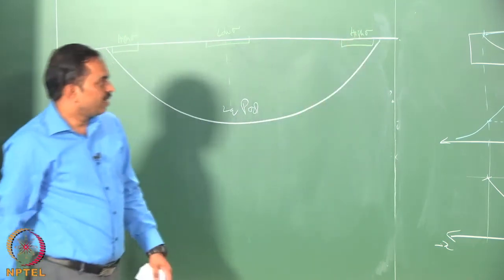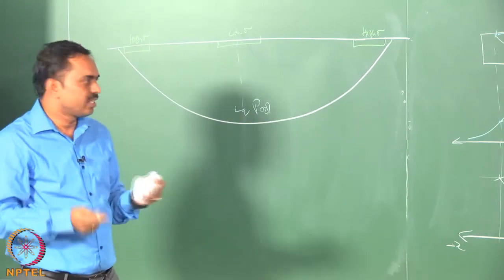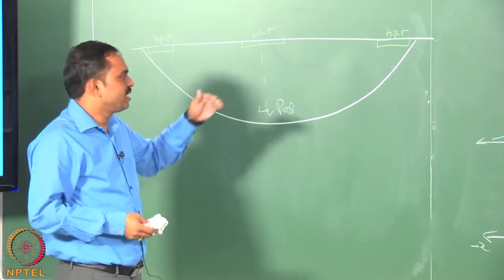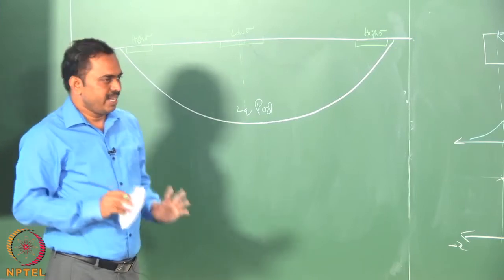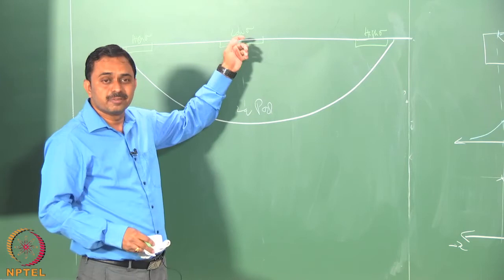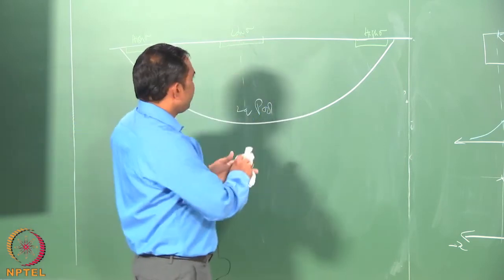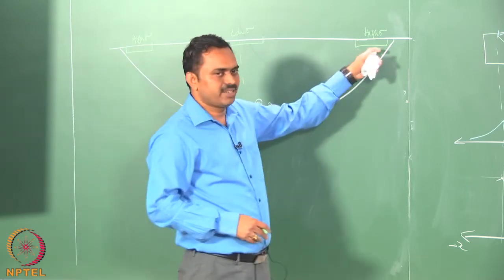And the reason why the liquid in the melt pool is going to convect because of surface tension gradients is essentially to minimize the surface energy contribution from the whole surface, and the way it can minimize is by having more area with low surface tension, or smaller area with high surface tension.